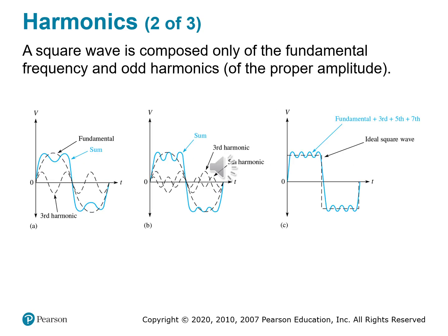So let's start with the building of a square wave, one harmonic at a time. What happens when you add sine waves together? Right? You shape new waveforms, and one of the best examples of this is the square wave. And here in this slide, we break it down beautifully. So a square wave isn't just a blocky signal pulled out of thin air. It's actually built from the fundamental sine wave and a series of odd harmonics. Let me walk you through this.